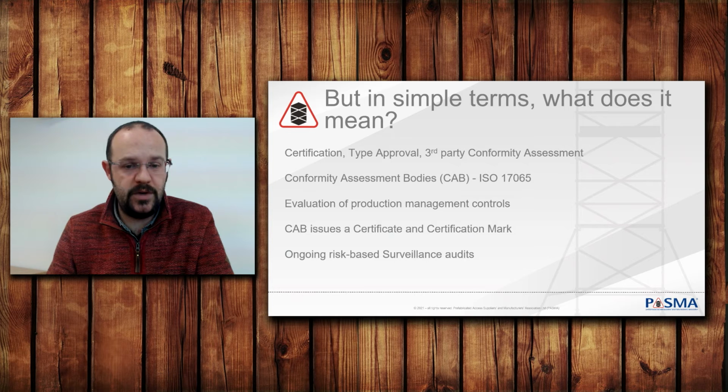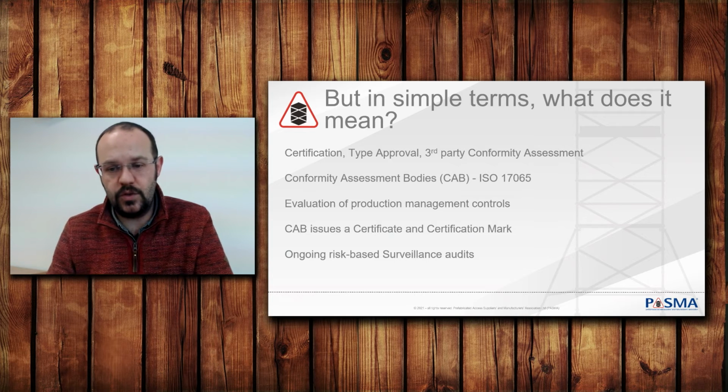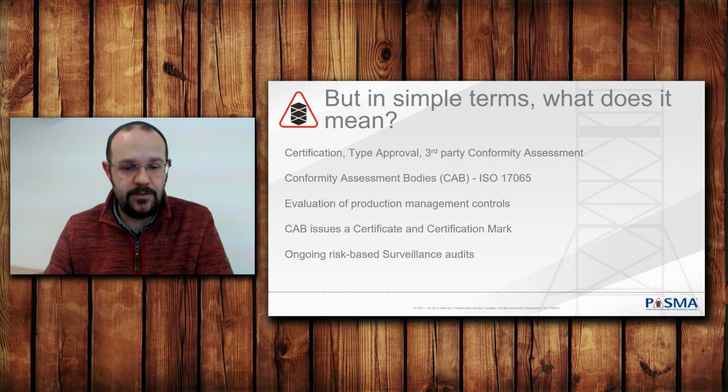The conformity assessment body will evaluate the product and establish if it is in conformity with the standard. In addition, they will also evaluate the management controls of the product's production. Evaluating the product and the production ensures that the item, as tested today, can be produced to the same design and quality level every time. The purpose of the production audit is to look at how the production is controlled. It looks at the management of the production, including goods inwards control, in-process controls, for example, production to drawings and management of jigs and fixtures, first-off quality assurance, warehouse and stock controls, and design controls, how changes could affect product conformity.